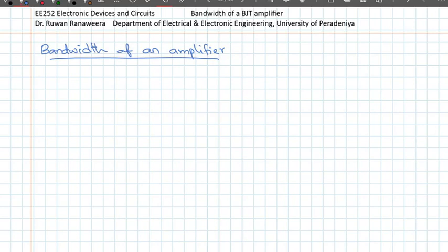So at lower frequencies, like 100 or lower than that, maybe 20, it may have a very high impedance, which may actually be comparable to the components that we have. In which case we can have a significant attenuation due to the voltage drop across these coupling capacitors.